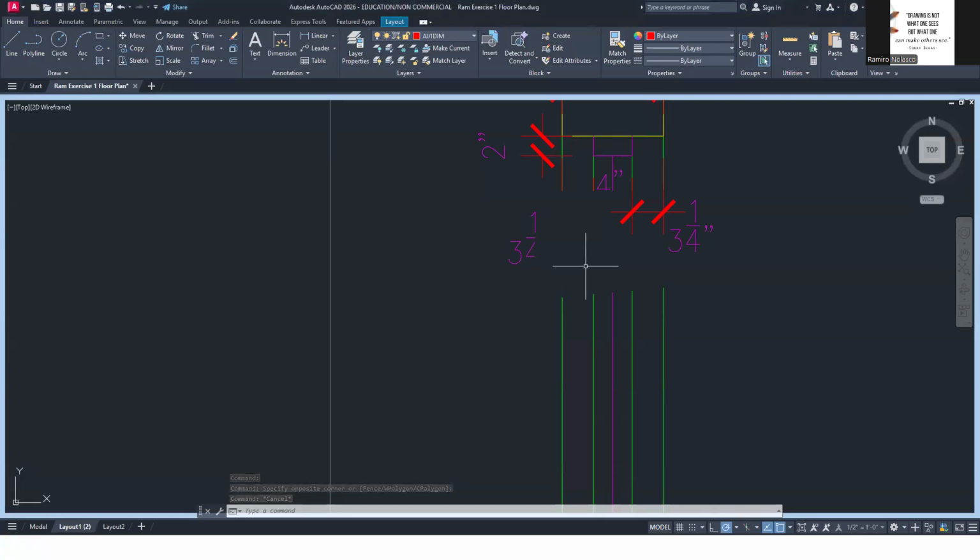Okay. So again, if you want to not show part, right, like to break it, you can do a wipe out. So this is a wipe out. Let me delete that. So wipe out, frame. You want the frame to be off, 0, 1 is on, and then wipe out. You can make a frame here.